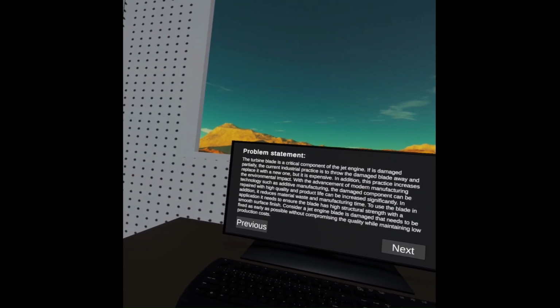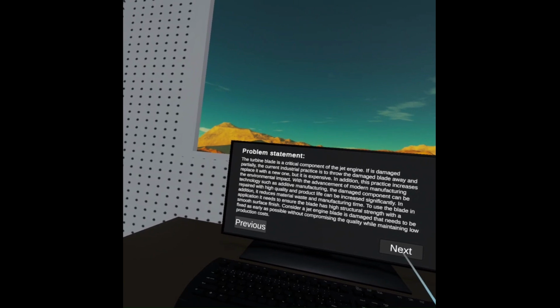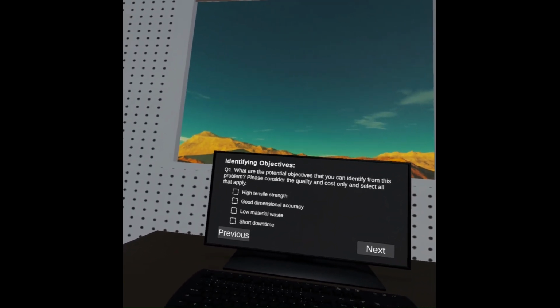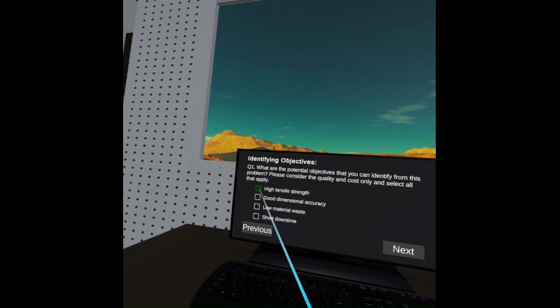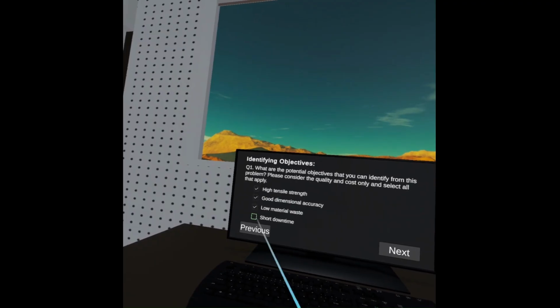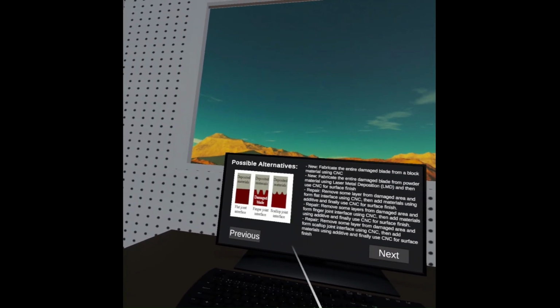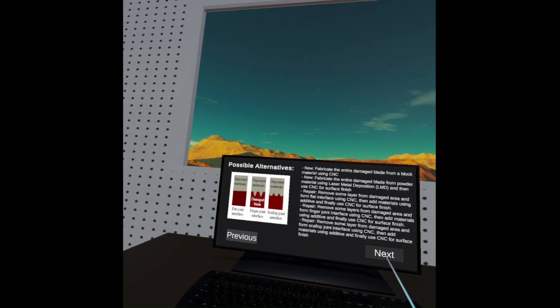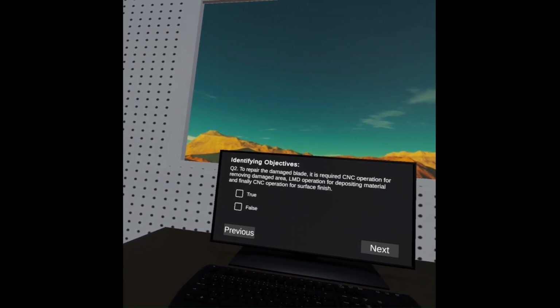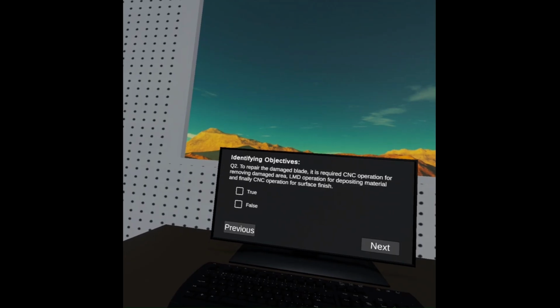Since the finger interface is a CNC plus additive plus CNC repair process, just like the flat interface, the only real difference in the machine preparation is that a different G-code program is loaded. All other steps, including powder loading, locking the doors, and laser activation, are identical to the prior method. However, we have included a full playthrough of the finger interface for thoroughness.